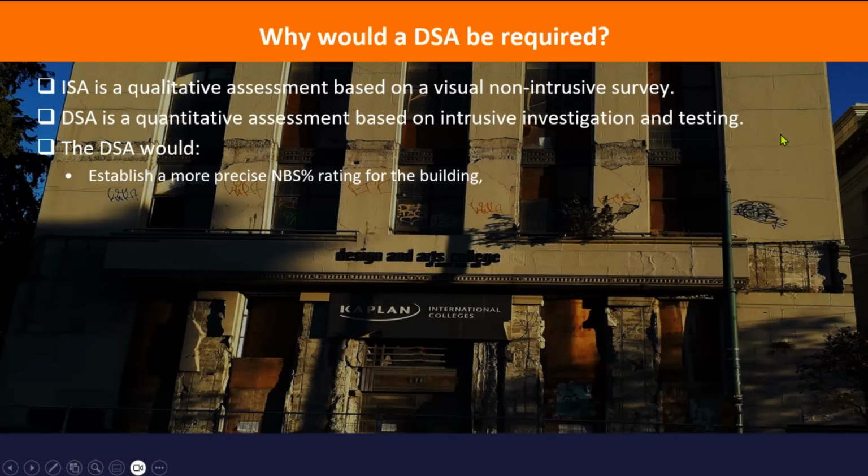That's one of the issues with DSAs, is working out what the strength of the materials was when it was built maybe 30, 40, 50 years ago, and they haven't kept the records. Now, things have changed in those past 40, 50 years. Materials are not the same as they used to be. Steel today is a lot stronger than it used to be. It's not necessarily stronger, it's just more reliably stronger than it used to be. Timber, on the other hand, is weaker than it used to be. Interesting.